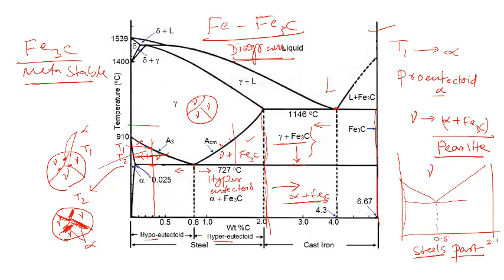So when you talk about cast iron and you come back to the phase diagram to correlate anything with regard to cast iron, you have to talk about the iron graphite phase diagram or iron carbon phase diagram. And you would find a little bit of difference in terms of these boundaries, in terms of the temperature at which these boundaries would form. Okay. So this is another thing that you should remember when you talk about the iron carbon phase diagram. Okay. So there are two aspects of it. One, you are looking at it with regard to the cementite phase, when you are considering that cementite is very stable and it is not going to dissociate as such. It may dissociate, but over a very long period of time.